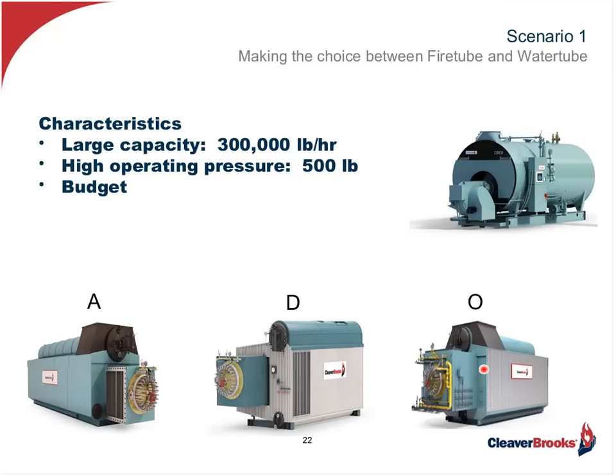So now it's just a selection of either an A-type, a D-type, or an O-type, which would give me the 300,000 pounds per hour at an operating pressure that would at least allow me to get to that 500 pounds. So you could have a 900-pound design pressure. The fire tube is limited to about 350-pound design pressure. So now because of the large capacity, because of the high design pressure, I'm again looking at my water tube as being the best solution in this particular case.